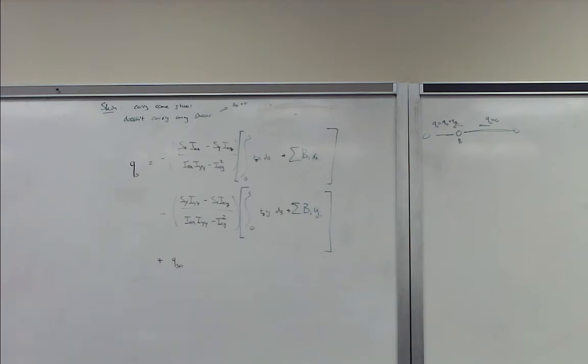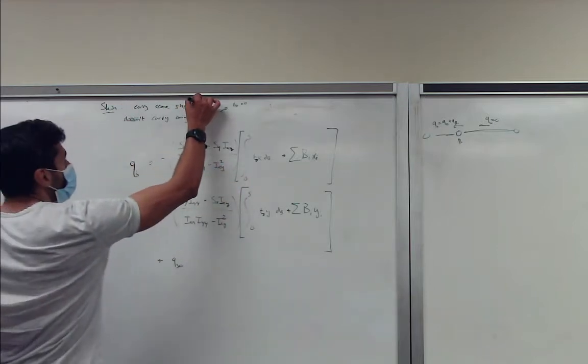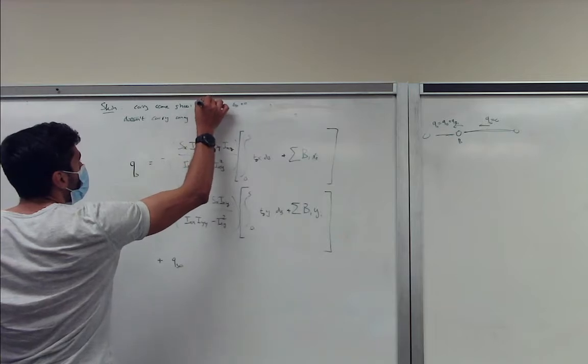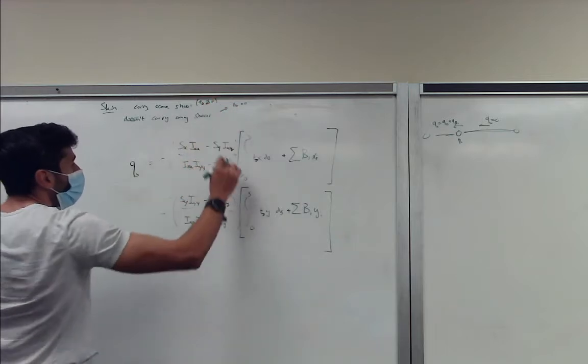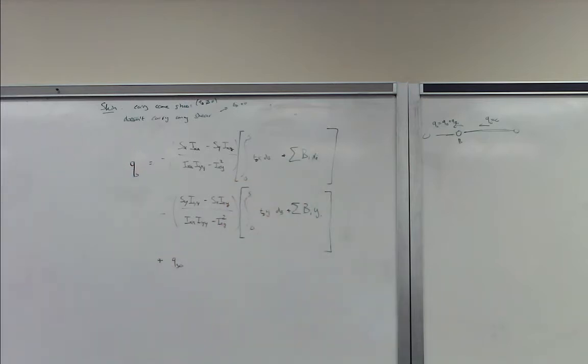So be careful when we do assume the skin carries some stresses. Then tD is no longer 0. So in this case, tD is not equal to 0, and you have both the integral format and the additional contribution of the boom area.